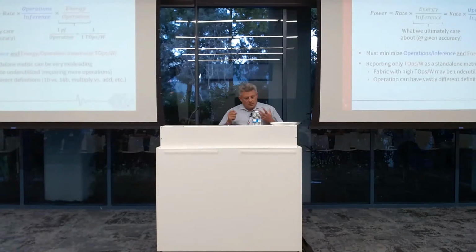So the second term in this product, energy per operation, is actually directly related to this TOPS per watt thing that I've been throwing around, because a picojoule per operation is the same as 1 tera operation per watt, right? It just depends on who you ask. Analog guys like to talk energy. Compute guys like to talk TOPS per watt. But it's actually the same thing, unit-wise. And so if you dissipate 1 picojoule per operation, that's like achieving 1 tera operation per second per watt.